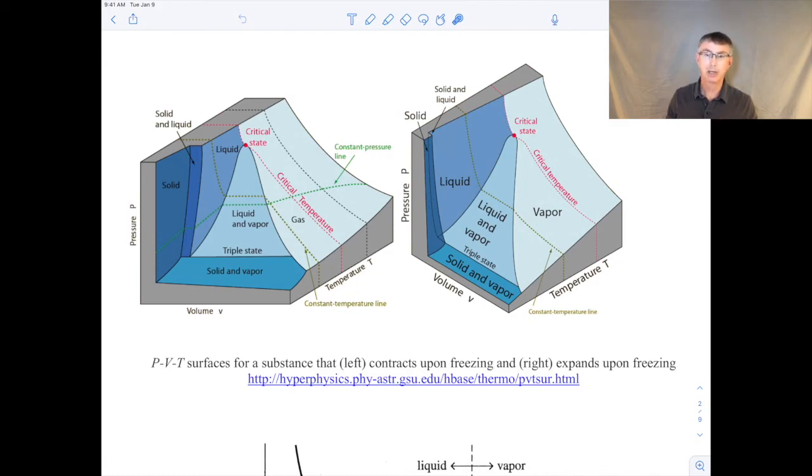The simple compressible systems we'll be focusing on will be pure water, as well as mixtures of gases that don't react. The mixtures of gases will be far from the point at which they condense into liquids, so we don't have to worry about some components condensing while other components just remain as gases.